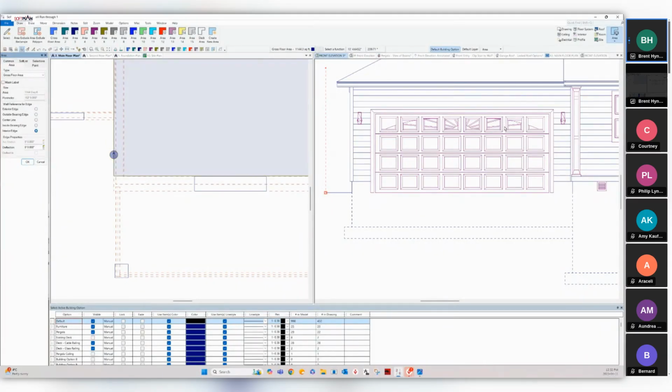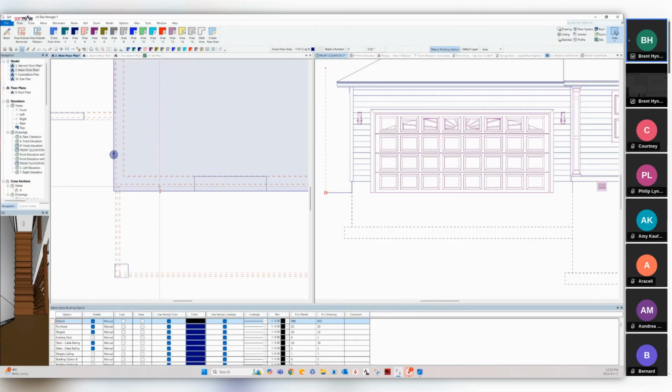It'll automatically move between all those points for you. Makes it a lot easier. In the past, you would have had to do an adjust and pick on that edge and adjust it to where you want it to go. Now we can just do an edit, and you can quickly pick on those and move them to where you want.